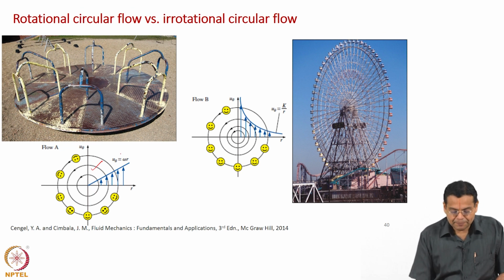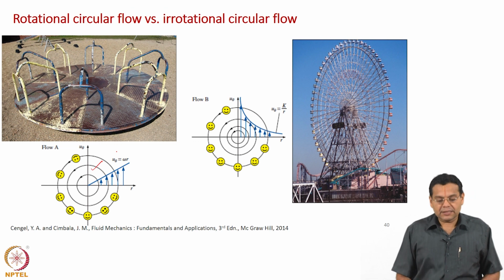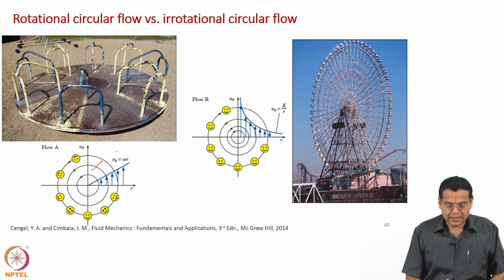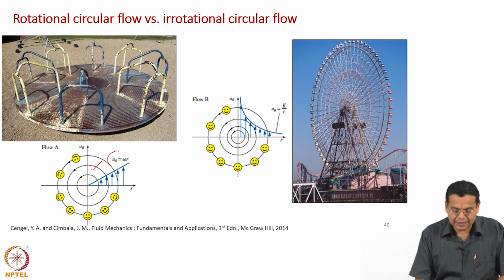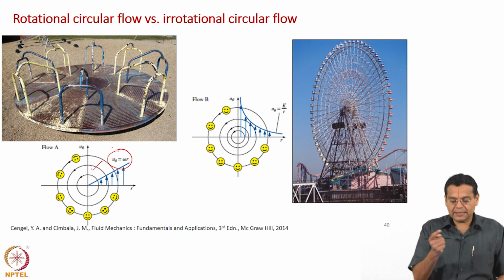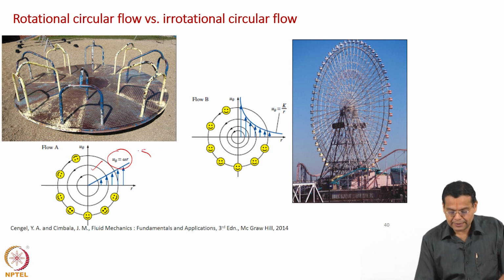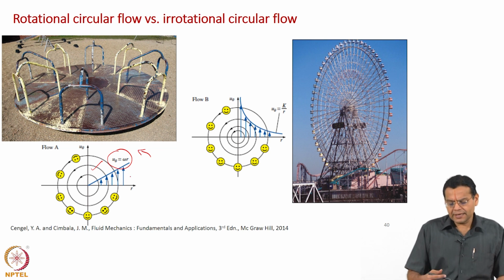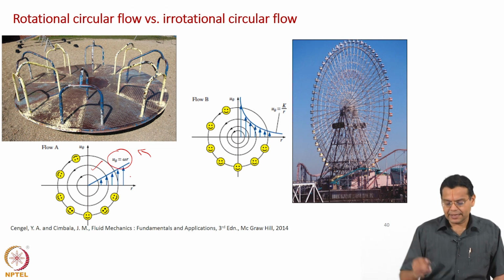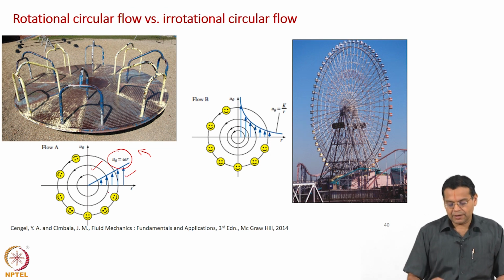Because we are discussing circular rotational flow, we can't avoid polar coordinates, though we avoid them as much as possible. So, what is shown here is u theta. What is u theta? Velocity in the tangential direction, the theta direction, and that varies linearly with r, the radial direction, and that is what is shown here. And this is circular flow showing streamlines and the velocity vectors.